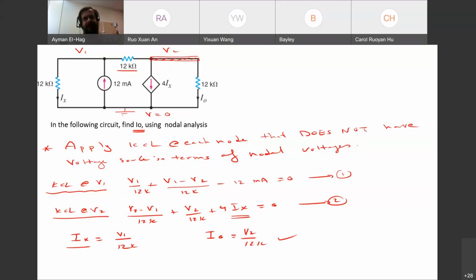Here we don't have any voltage source, so we use the bottom as ground. It's always very convenient for us to do that. Then you find every single node voltage, which is n minus 1, because at the ground V equals 0. So I already know that voltage, and I need to know the voltages on all other nodes. Once I know V1 and V2, I can now see the question, what you want me to find.